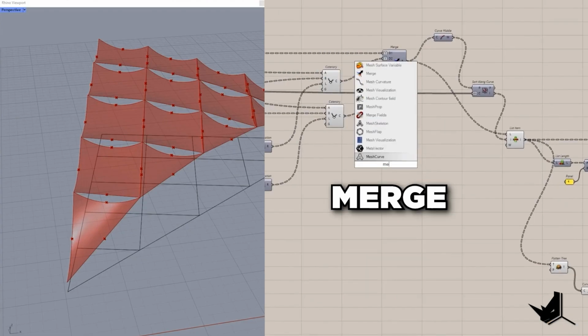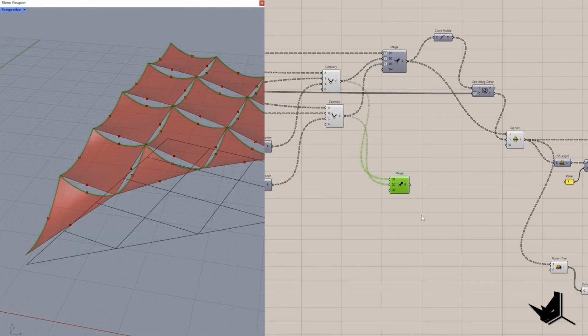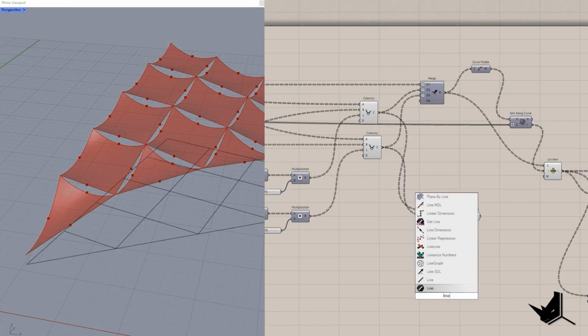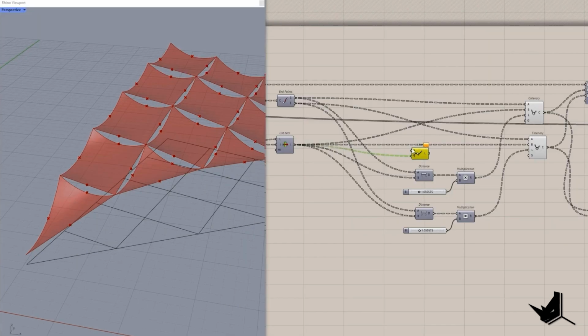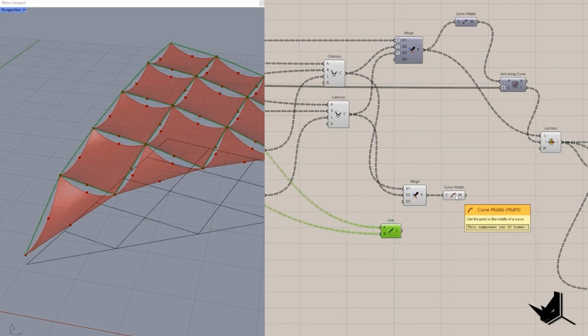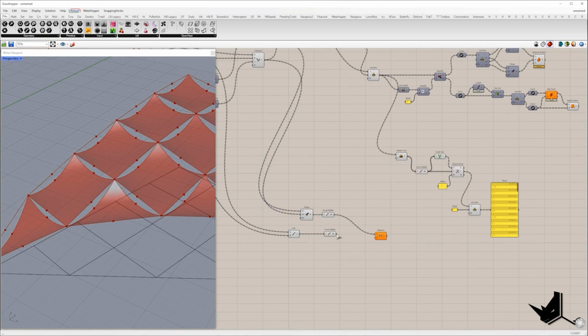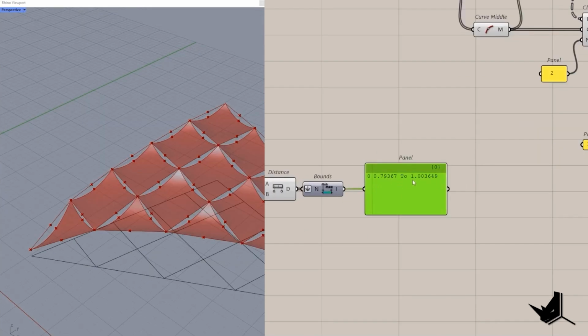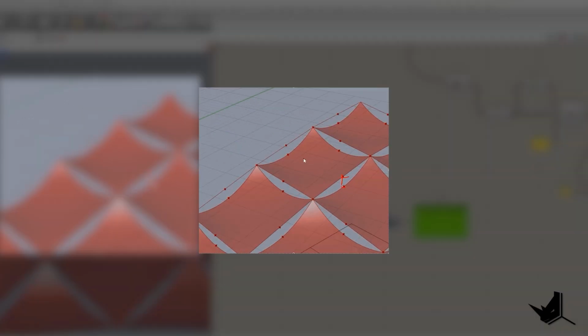This range we can find if we take these catenary curves and extract middle point, and also middle point if we create a straight line from these guys. So let me connect these endpoints, and here we have straight lines. Also we can extract this middle point. We can calculate these distances, and I will use bounds to create a domain. Don't forget to flatten the list, and here we have minimum and the maximum distance from these 2 points, only considering vertical dimensions.